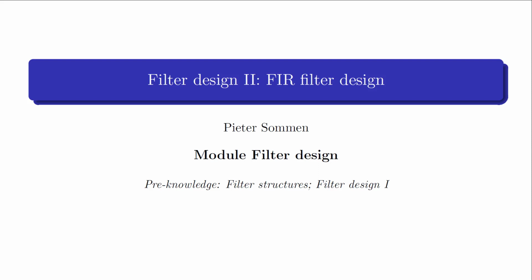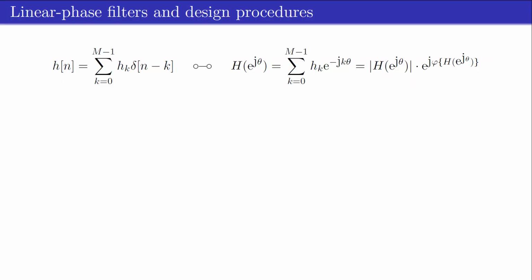Welcome to this video in which we will discuss some commonly used design approaches for FIR filters. The frequency response of an nth order causal FIR filter is given by the shown equation, and the design of an FIR filter involves finding the coefficients h_k that result in a filter response that satisfies a given set of